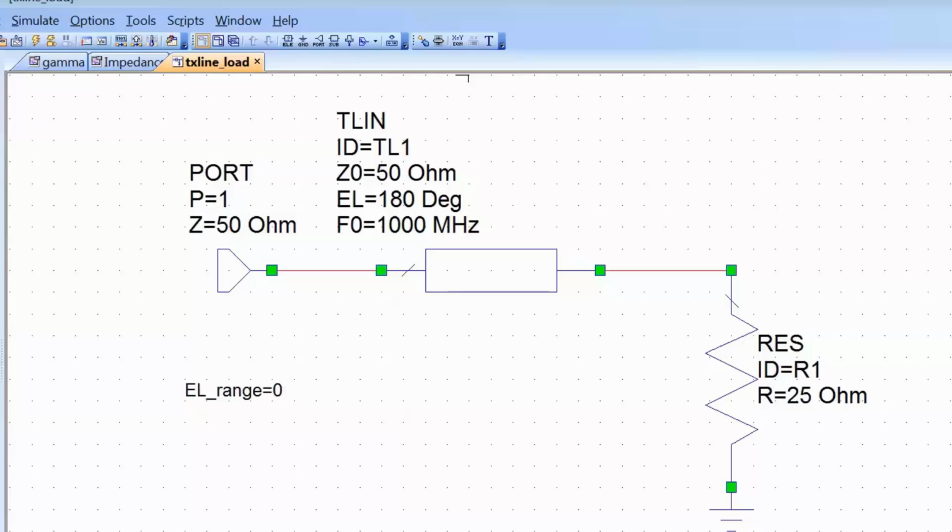This value is completely immaterial. I am just defining a variable which I will then sweep, and I have to, because of the way the simulator works, declare this variable separately and give it an initial value. Then I can connect it to the sweep element, which we'll get in a moment.